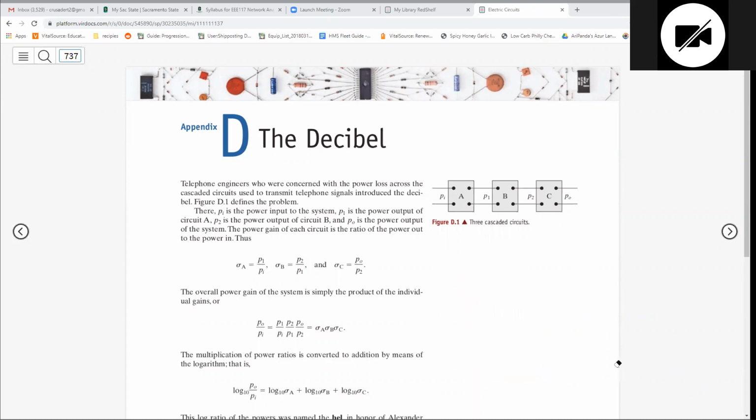Depending on how you build your circuit, you could do any of that. But we need to graphically show what the characteristics of the circuit are, where it actually turns on, where it turns off. We need a little mathematical detail here, and that's what Bode plots are. It's a graphical representation of the frequency domain and how the circuit operates. And it ties into Laplace transformations. The whole idea is we have a circuit, we do Laplace transformations, and figure out a transfer function. A transfer function has poles and zeros, and with the poles and zeros, we can figure out how the circuit is going to behave in terms of frequency. That's the big picture of what we're trying to do.